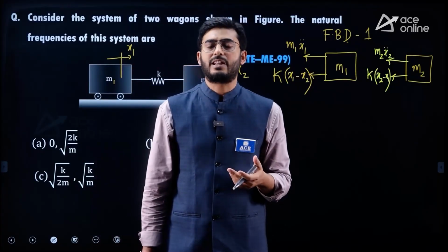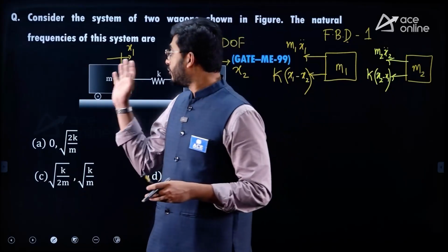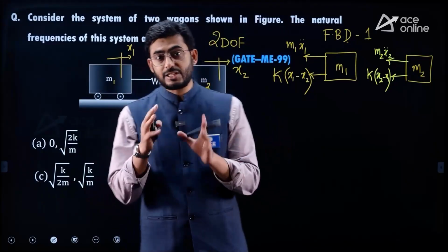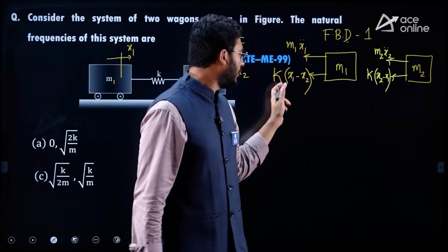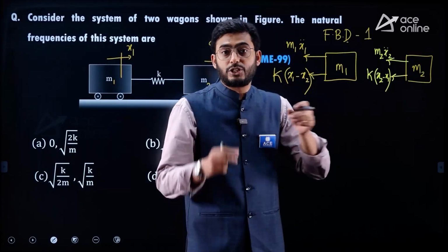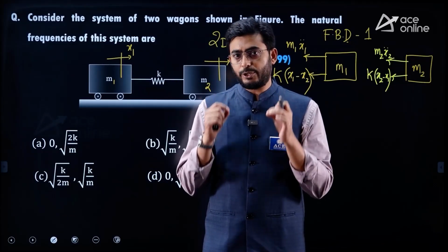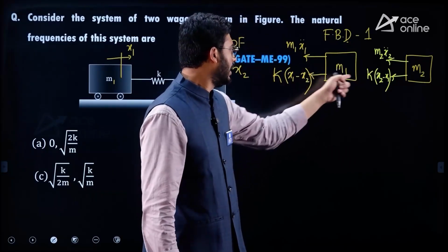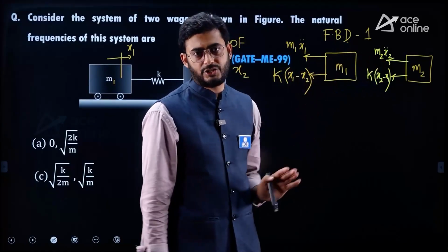That's how the reactive forces or connecting forces are transferred from one body to the other body. And this principle we have learned in engineering mechanics. The same is being used. It is just that we modify the direction of that reactive force, the connection force that is responsible due to the connection. Here we are reversing the direction of the force when the bodies change.